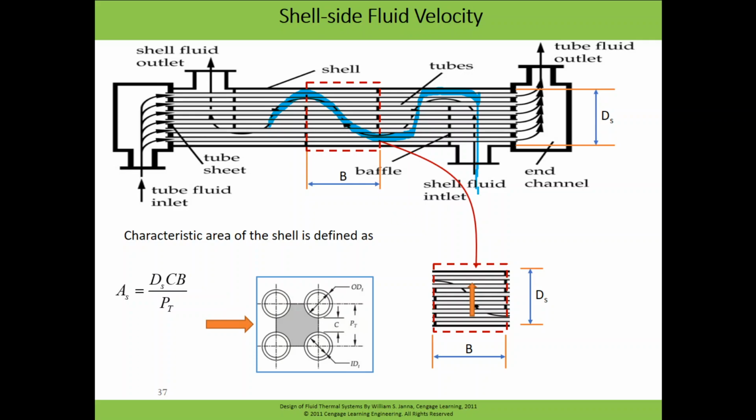So we can approximate that the fluid in the shell and tube is passing through the tubes like this from top to bottom, and there are baffle spacings, and then it is going like this. Okay, so if we consider the 1 unit, in this 1 unit we are considering that the fluid is passing this way. So when the fluid is passing this way, in the space it has tubes across this, so it will face the tubes perpendicular.